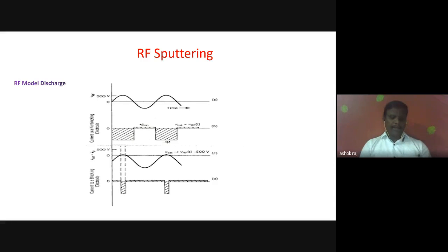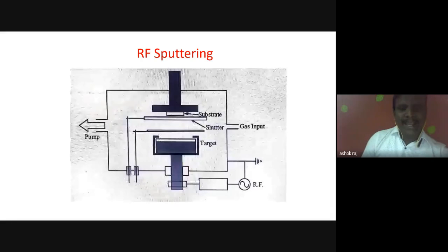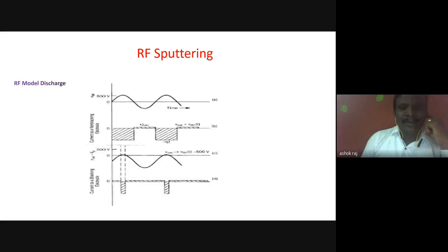Here all the parameters are chosen to have a charging time of the blocking capacitor, during the electron bombardment on the target, not much greater than one radio frequency period. Using these four RF modes, we can coat the high quality desired thin films on the substrate.